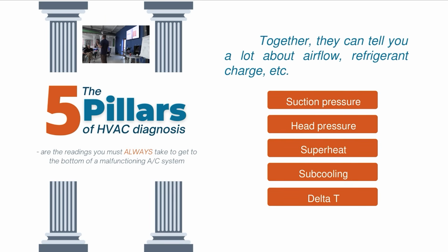In addition to these 5 things, the 5 pillars, which I realized later on, has anybody ever heard 5 pillars before? Apparently there's the 5 pillars of Islam. I didn't know that when I first created the 5 pillars, and somebody brought that up to me. That wasn't intentional. I'm not trying to co-opt. So suction pressure, head pressure, superheat, subcooling, and delta T are what I call the 5 pillars.